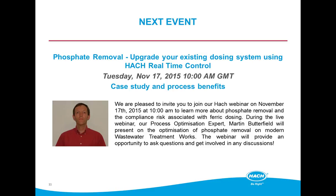The actual filter itself is designed to be used in a crude sewage application, so it's extremely robust. Depending on the site, because every site's different, it could maybe go 2-3 weeks without a change. But in practice, we advise just changing it over once a week to make sure. Basically, then it becomes habit forming. If it's every other week, then experience has shown that it tends to get forgotten about, and then that can become a problem. But the actual swap out procedure of the TMS filter is super easy.